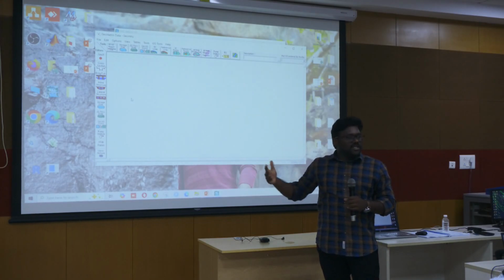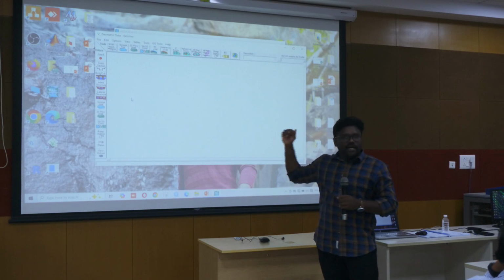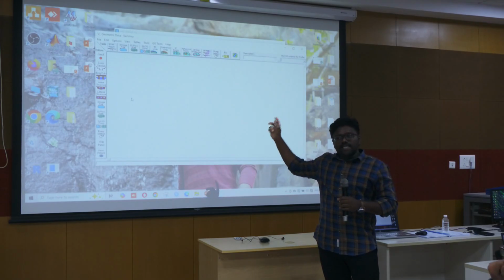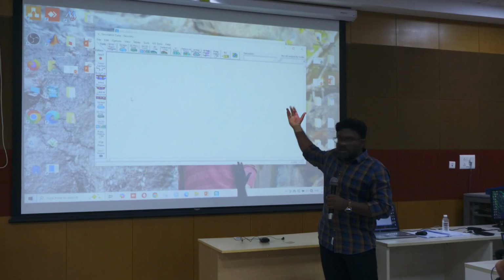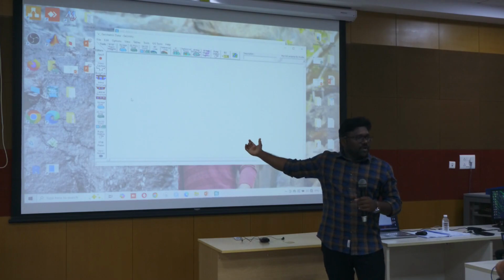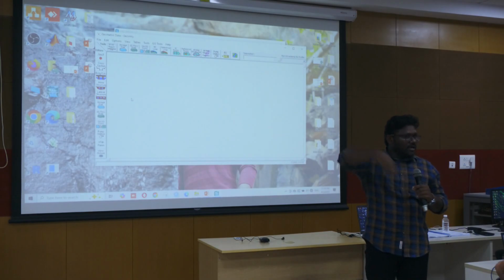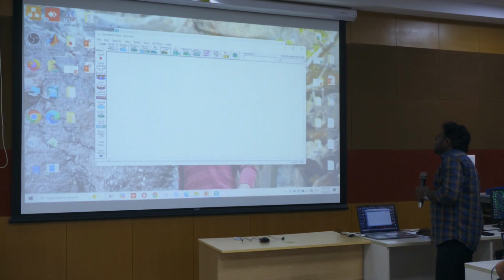Now, in the newer versions, the GIS has been included, and that is nothing but RAS Mapper. Using RAS Mapper, we can draw all those lines, and they will be visible here. Otherwise, it is difficult to know where the river is going from and to.